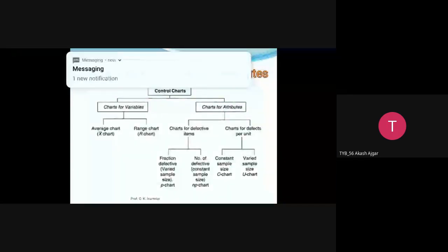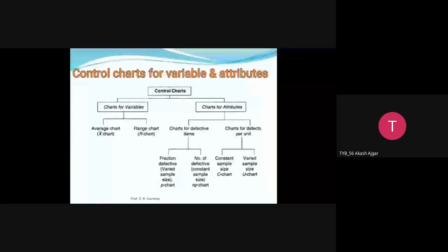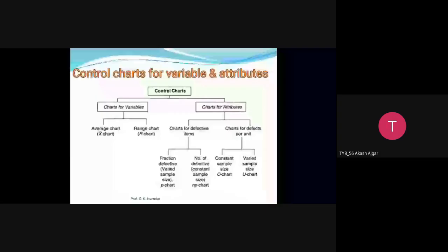Variable charts as compared to attributes. All the data is already available from the respective records. The process seems simple to understand as compared to X bar and R chart. So as compared to variable charts, in attribute charts all information is already available, and it is very simple to understand, and it provides an overall picture of quality history. Basically, attribute charts are easy to understand, easy to draw, and provide all the information regarding quality history.